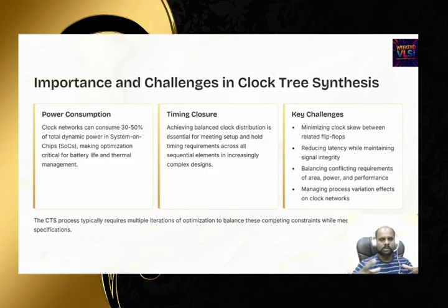If you reduce the skew, your setup and hold will be better. If your skew is high, then after you have completed your placement, whatever timing you have closed may not hold good. That's why it is important. And hold is very important here because skew directly affects the number of buffers you add.